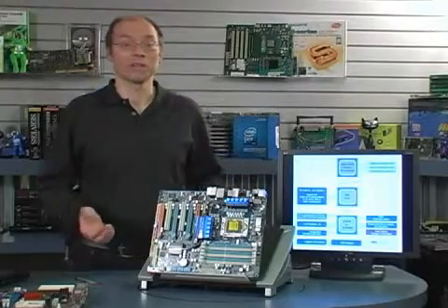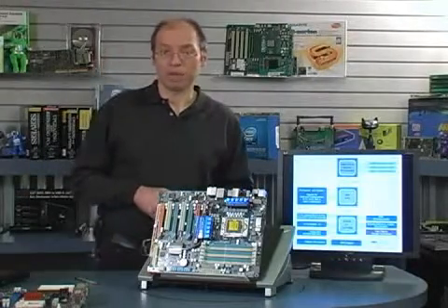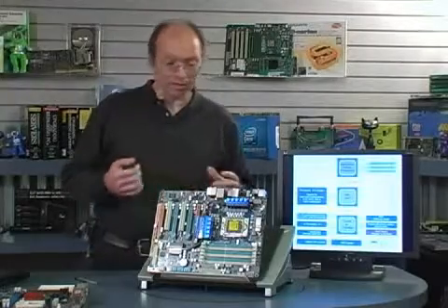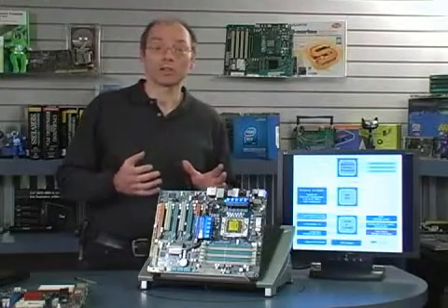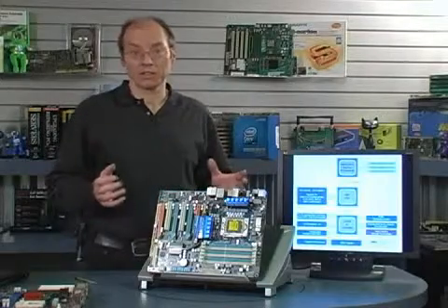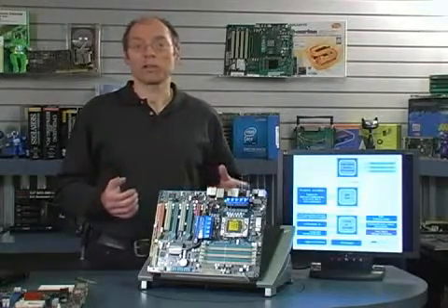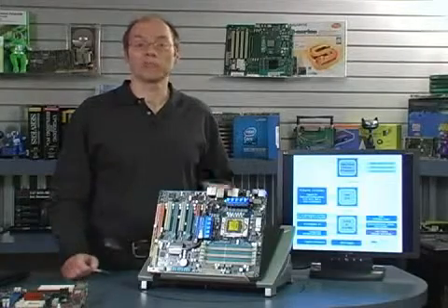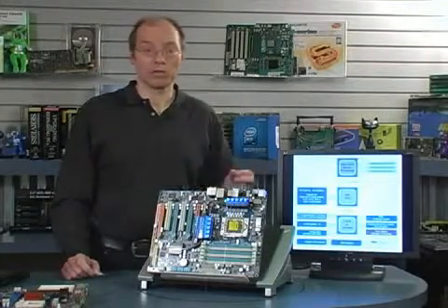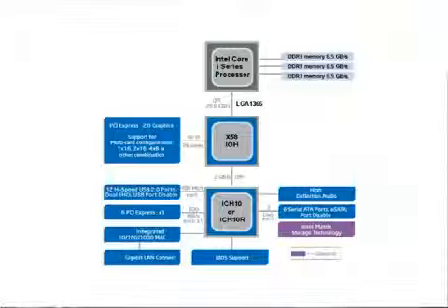I know a lot of people think of the processor as the most important, but the motherboard is what the processor itself plugs into. Now, normally when you're putting together a system, buying or building, you're going to decide, I want this certain type of processor. Then that gives you a range of chipsets to consider. See, the main circuitry on the motherboard is what we call the chipset. Now, modern motherboard chipsets normally consist of 2 chips, what we call the north bridge and south bridge. I have a diagram here showing a typical motherboard block diagram, and the north bridge and the south bridge are these components here. The processor would be in the socket represented by this top portion of the diagram.